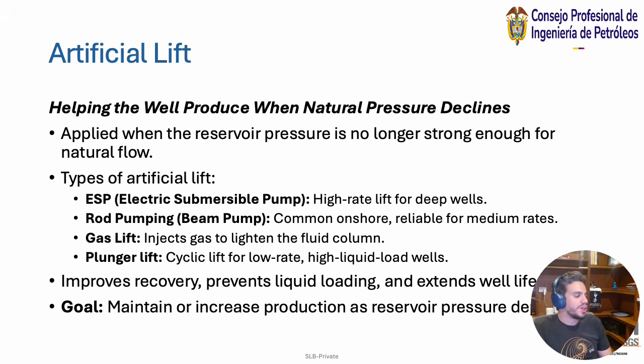And last but not least is the artificial lift. So this is also another form of the strategy of what we're talking about, that we want to improve the production of oil, but this comes in more of the final stages or in the secondary stages of recovery, right? Because when we first drill and we perforate and we're producing oil, we're relying on the massive pressure of the reservoir that's sort of pushing the fluid into our well, and we're just producing based on the reservoir pressure.